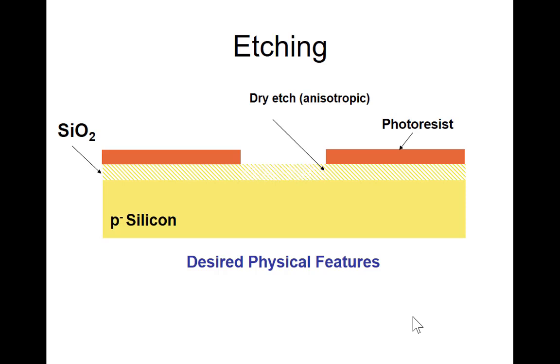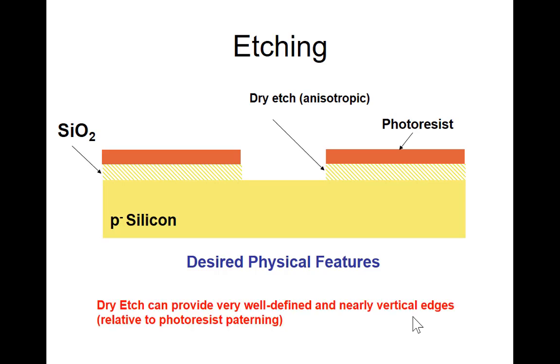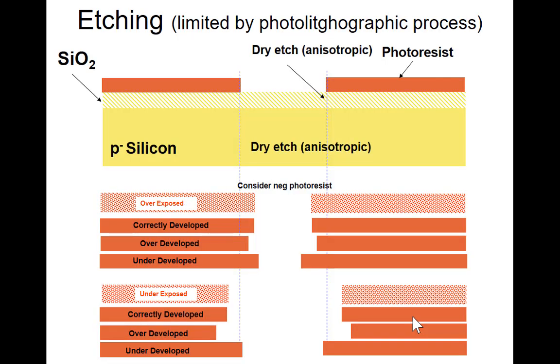So for dry etching, you can achieve a very good anisotropy. You get it nearly equal to 1. So then quite vertical. And for wet etching, it's more likely to get those problems that A is not equal to 0 and C is not equal to 0. And that A not equal to 0 could have another cause. It could be due to the photomasking processing step.